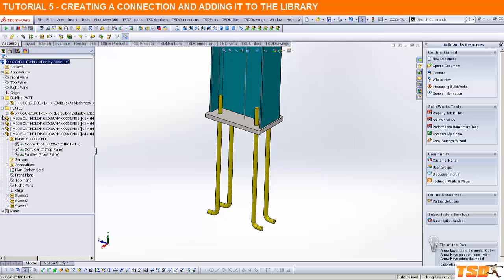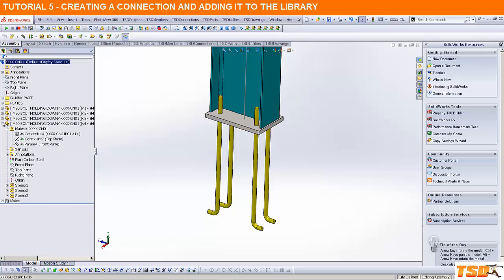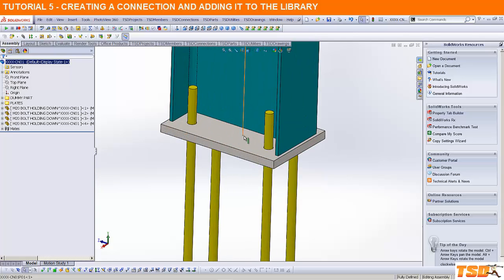Now this is just a base plate that has no grout. If you were going to add a grout piece underneath this so that you would lift the plate up off the ground or off the origin by putting a bit of a space under there to grout it, you would actually position your plate in such a way that it was offset. You don't need to show grout, but you can.